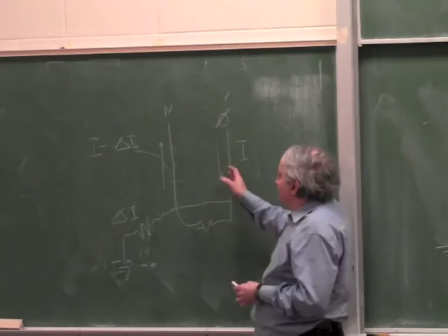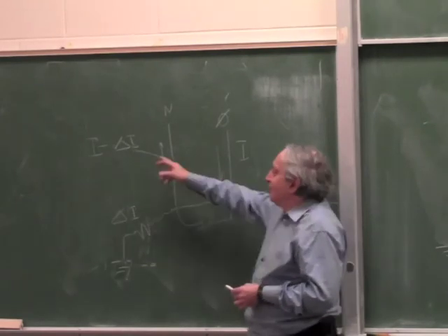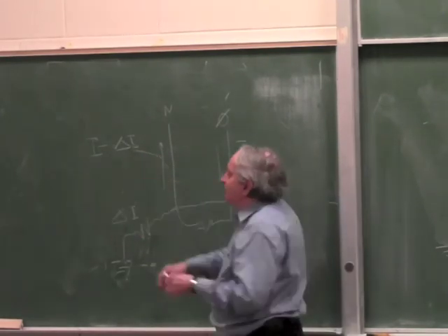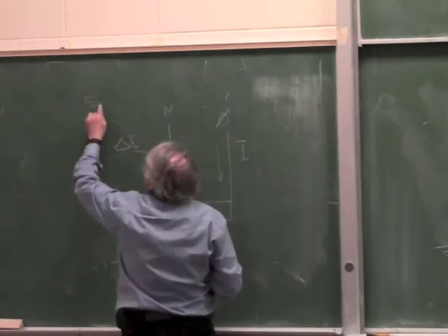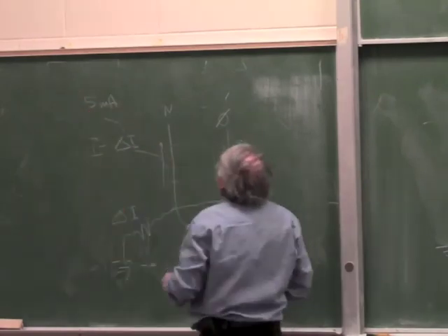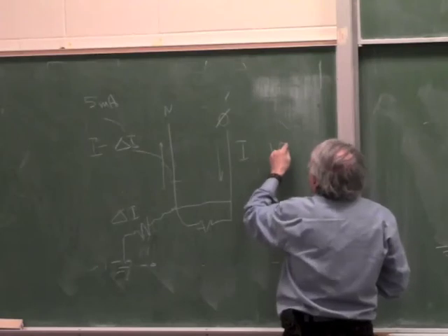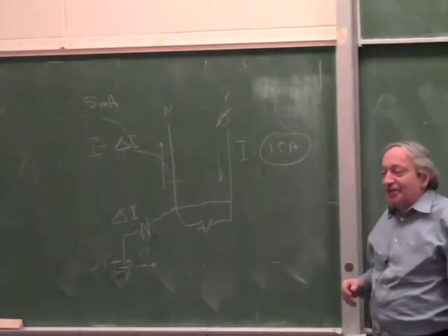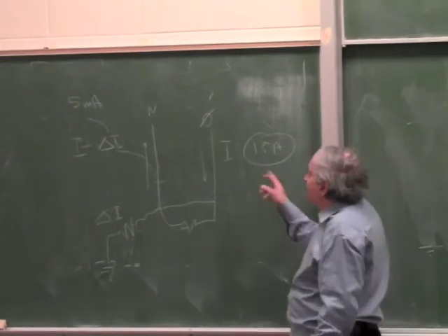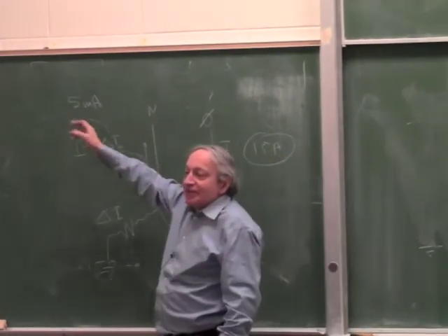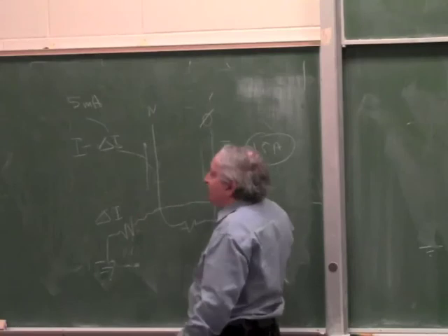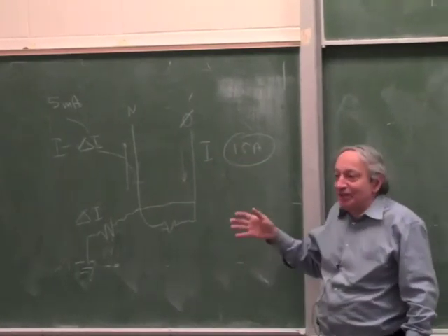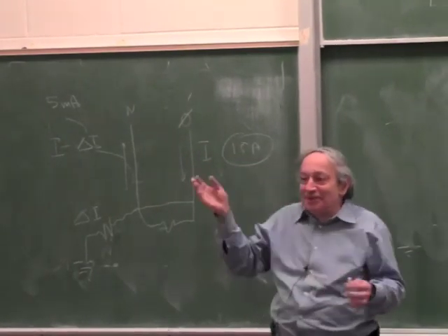So how does it physically, this is a very small difference. Typically the GFIs are set for 5 milliamps. That's the code. And this is actually 15 amp, because the outlet will give you 15 amps. So how can it detect a 5 milliamp leakage on a 15 amp current for $10? Because it's a very simple thing. You can buy it in any hardware store.